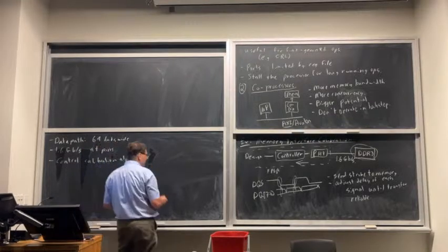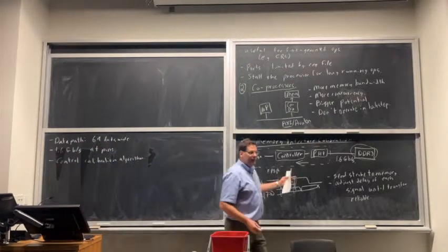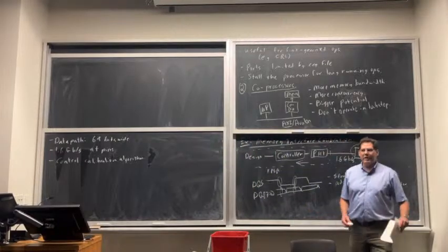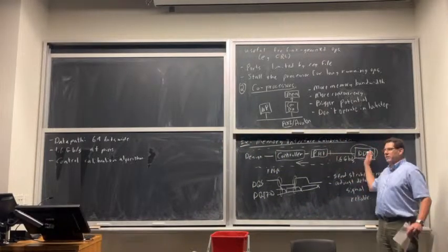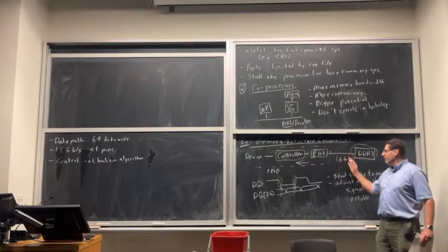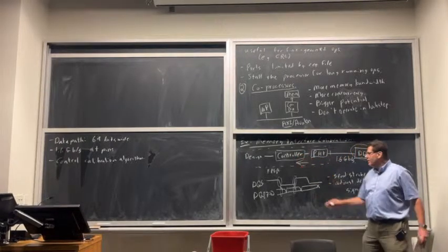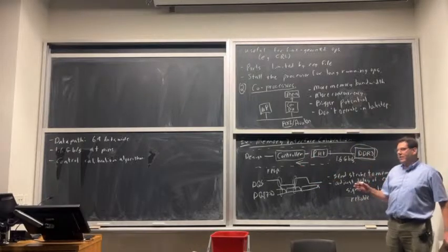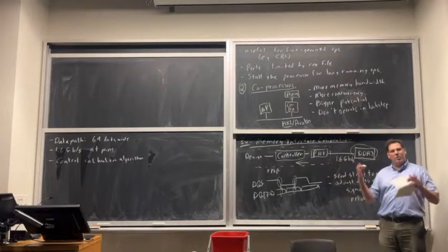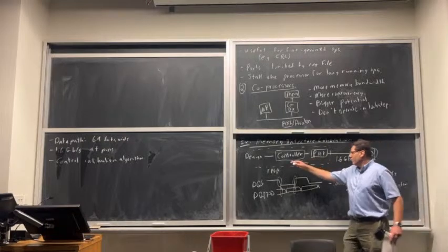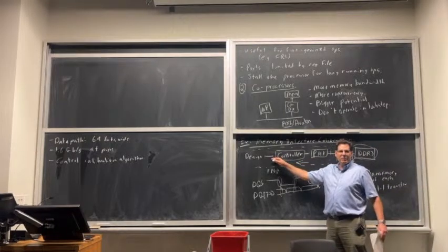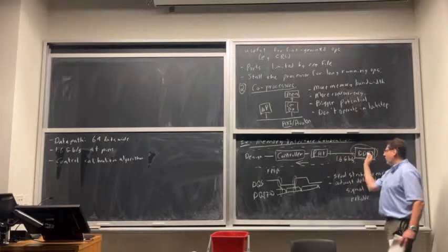So basically when an FPGA or anything wakes up, let's just take an FPGA, it wakes up and you've got a DDR interface on the other side of the board and you want to use it. So you put this IP in that Intel or Xilinx gave you. And what it does is before your design gets programmed in, and before this controller will accept any commands from your design, it actually starts talking to the DDR.